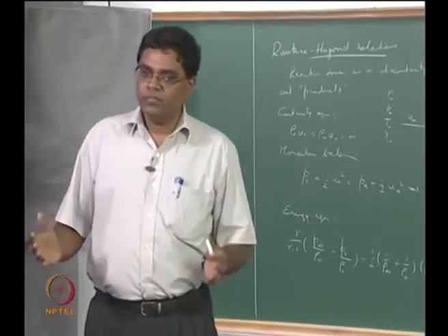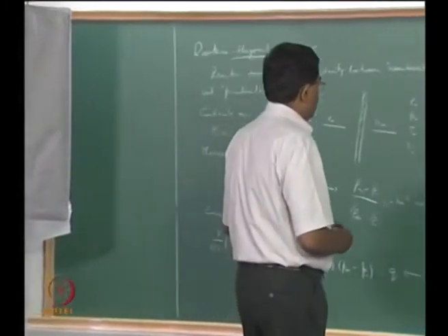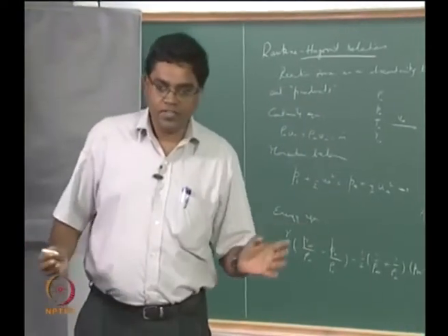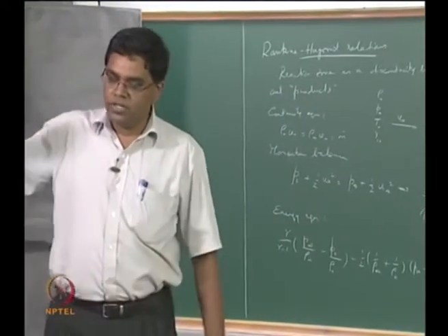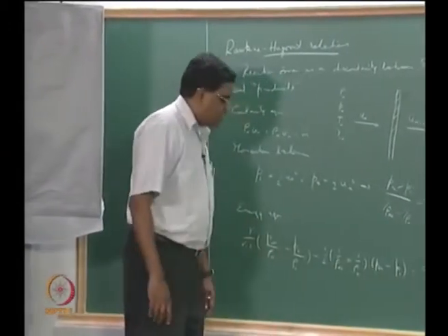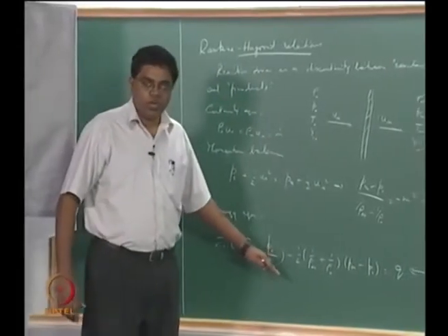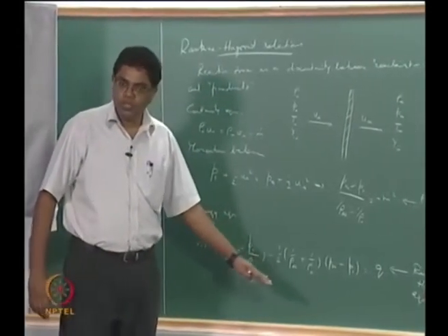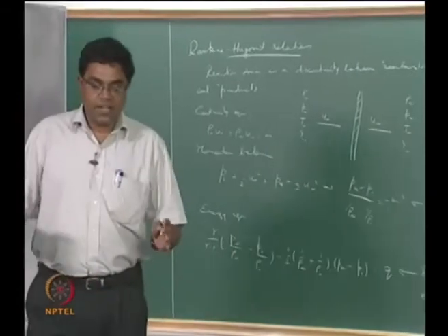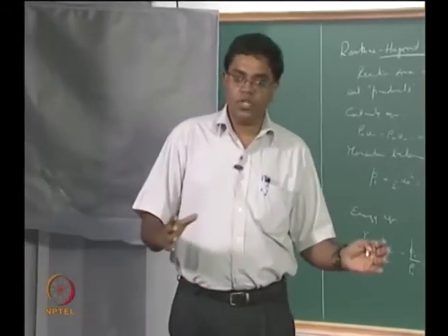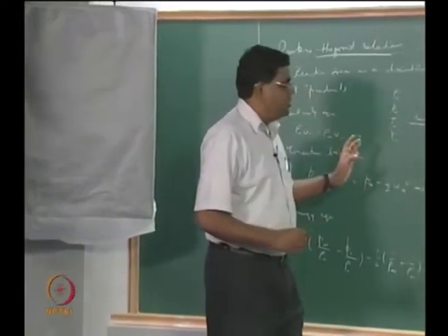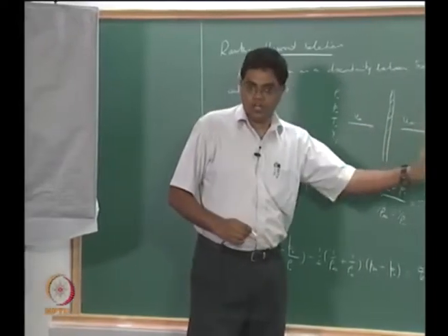So if a chemical heat release is not there, essentially we are talking about a non-reacting mixture. A non-reacting mixture with a Hugoniot curve is somewhat similar to what you might have gone through in a basic gas dynamics course. If you think about how we had the equation H naught plus half U naught squared equal to H infinity plus half U infinity squared, that is without the Q. And that is exactly the same as the adiabatic energy equation that you would write for energy conservation across a shock.